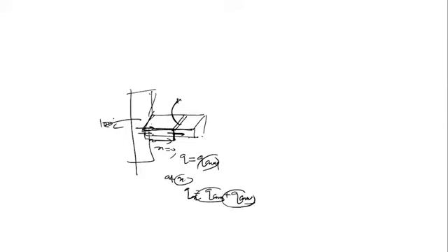But within the solid or within the fluid alone, it's not possible. If I'm talking about only fluid, Mr. Prasad, is there simultaneous conduction and convection in only fluid? No, because what happens at the wall, again the same concept, on the surface of the wall the heat transfer is via conduction, but that is the same as the convection. Q conduction equals Q convection, because this is the wall, and this is the fluid flowing over it. At y equal to 0, heat transfer is by conduction, and that propagates by convection. Yes or no?